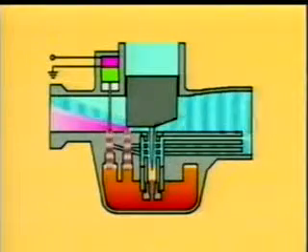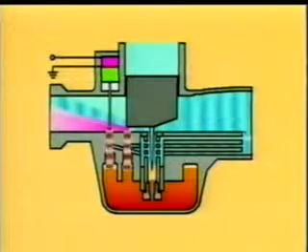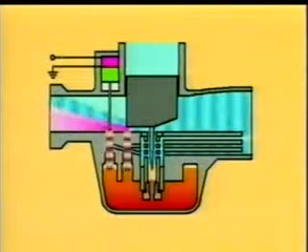A simplified diagram of this system would look something like this. When the engine is cold, the wax is also cold, so the starter valve is pulled upwards and a rich fuel-air mixture is sent to the engine.